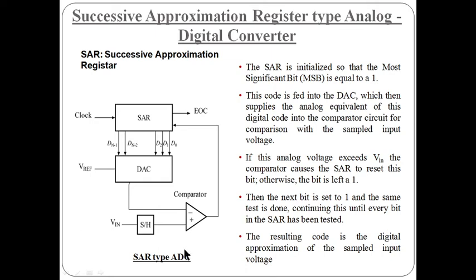The input of this SAR is the comparison result between the DAC output and the incoming voltage V in. A successive approximation register circuit is used to provide an approximate digital code of V in to the internal DAC. This SAR provides input to the digital to analog converter, and the output of this DAC is compared with this incoming voltage, or sample voltage, inside the comparator.